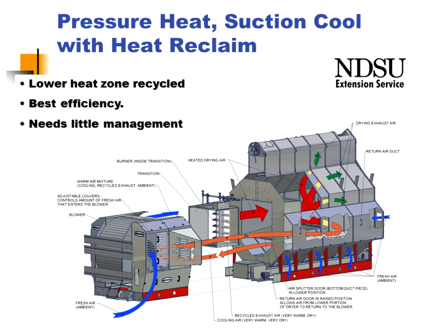Cycling that back through the fan and being used then to preheat the air going into the rest of the dryer. This is by far going to show the best energy efficiency. We're dumping the corn cool out of this dryer, so it does not require near the management of in-bin cooling, and we'll go through that in a little bit later.